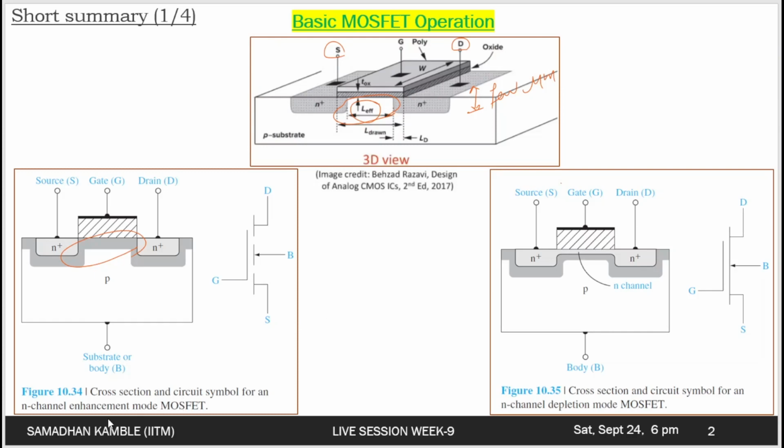So this is the N channel enhancement mode MOSFET, and implicit in the enhancement mode operation is the idea that the semiconductor substrate is not inverted directly under the oxide with zero gate voltage, and a positive gate voltage induces the electron inversion layer, which then connects the N type source and N type drain. So this particular channel is created in the enhancement mode.